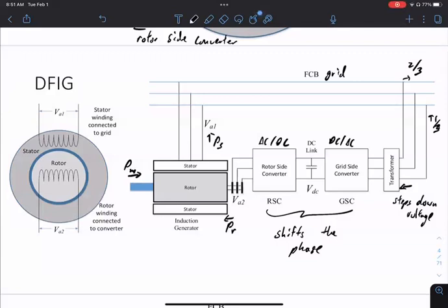Basically in the 90s, we could build these, and the controller was good enough to do control. Even today, if you work on wind turbines, a lot of work still happening is how do you design a better controller for this under different circumstances. What if there's a fault? What if there's a short? What if you want to temporarily provide more active power? There's a lot of design still going on. Most comes from designing these converters and the controller for these converters.